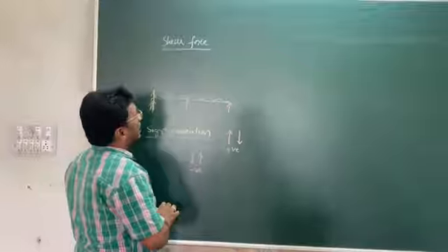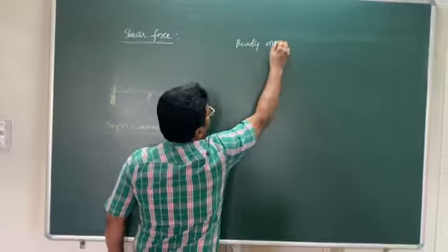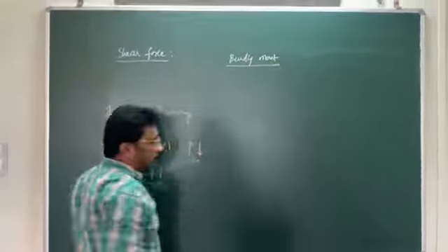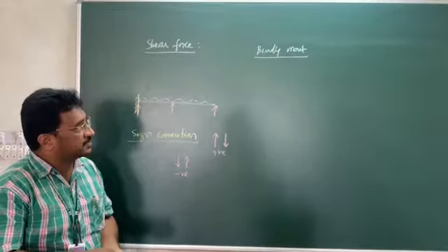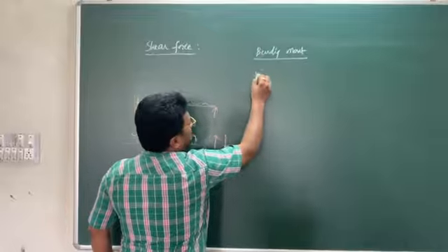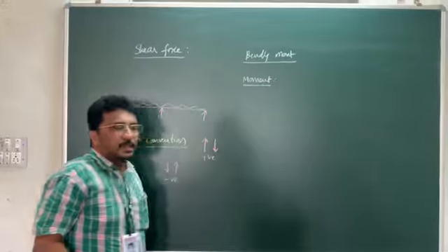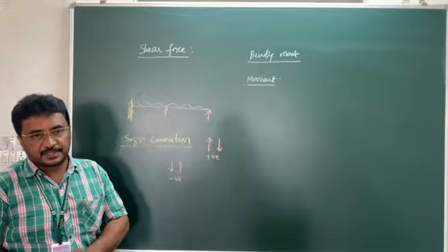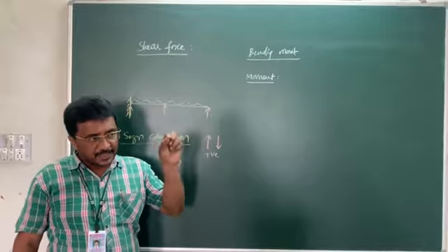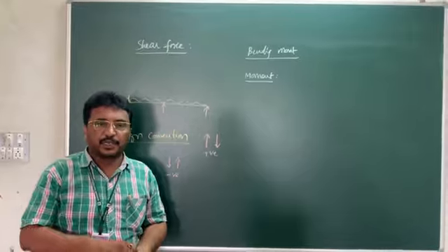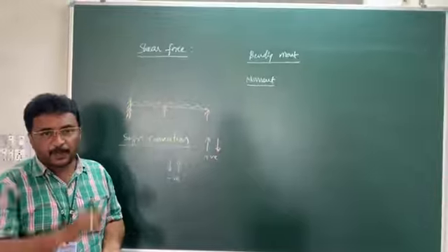Similarly, while I am talking about the bending moments here, what is bending moment? Bending moment is nothing but the algebraic sum of the moments. But before discussing bending moment, we should know about a moment. Moment is nothing but the product of force and the perpendicular distance. Whenever any structure is subjected to loading, at any section, if I want to calculate the moment, at that particular point the moment is equal to load times the perpendicular distance.